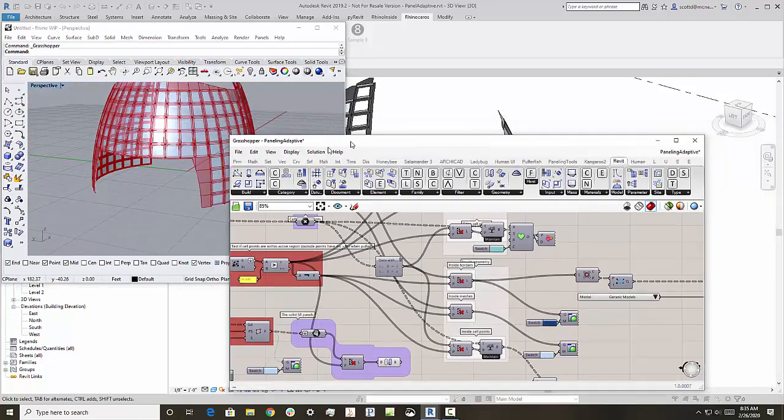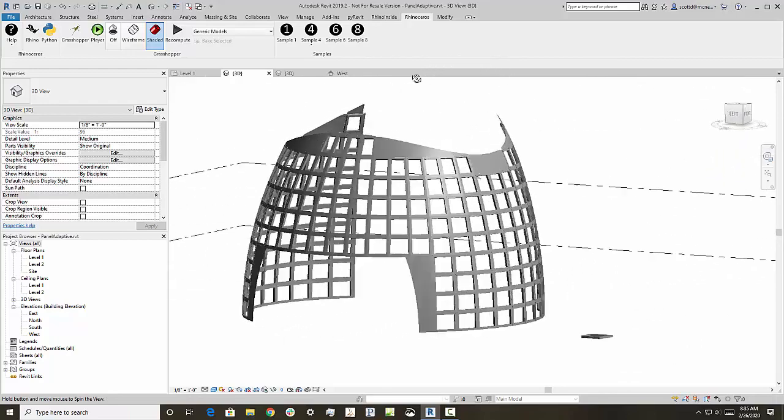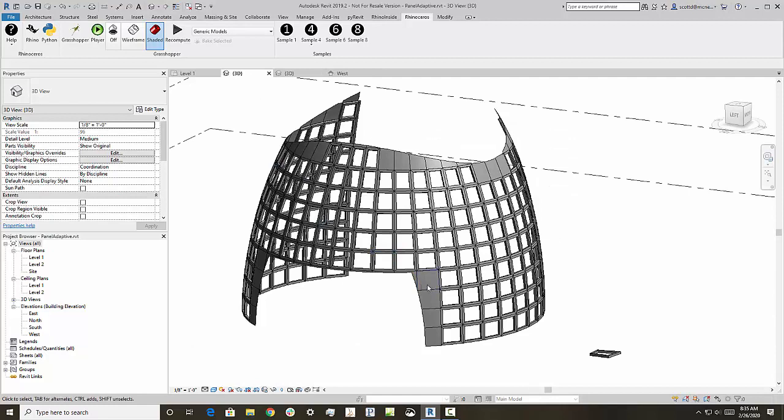And you can see over here, if I come over to the Revit model, we also have those panels as direct shapes. What is helpful there is, of course, they'll show up correctly in elevations. You can use them for your drawings because they're actual Revit objects. You can actually schedule them the same way that you would schedule the adaptive components. So these could all be scheduled with the same generic model object in this case. And you can add parameters and all that information.